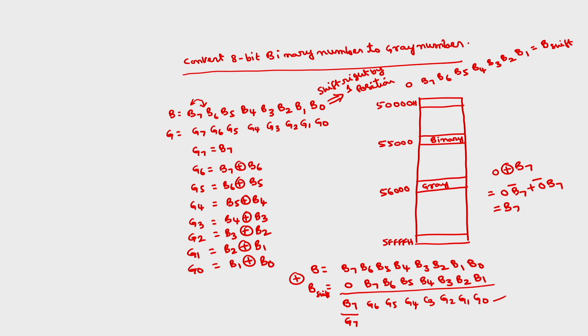Okay. The program will be, the first two instructions are the same: MOV AX, 5000, MOV DS, AX. You can even call MOV SI, AX also, because here the offset as well as the data segment are the same. You have assumed the locations such that both are the same. So, instead of moving the address, we can just directly transfer the AX content to SI also. Then CLC, this is important, the carry flag I am going to reset.